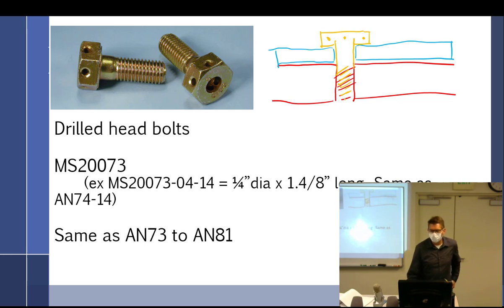All right, so there is no nut because the bolt actually just went into the part and the part had the threads. So that's what it's designed for. Now I can run the safety wire through here to something else. The part was the nut, basically. The part is the nut. So that's why I got the safety wire on there. So, of course, we don't forget to put a washer in there. Always got to have a washer.